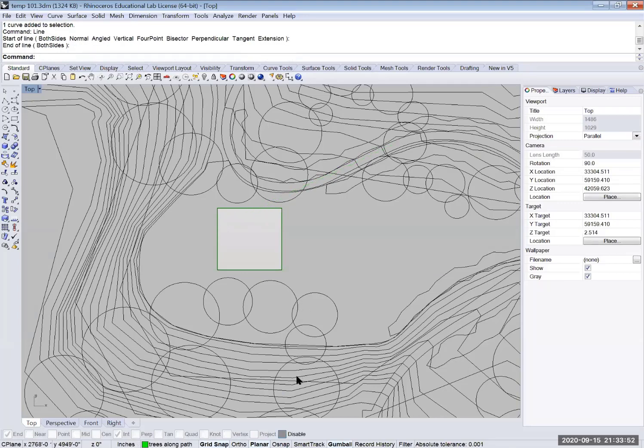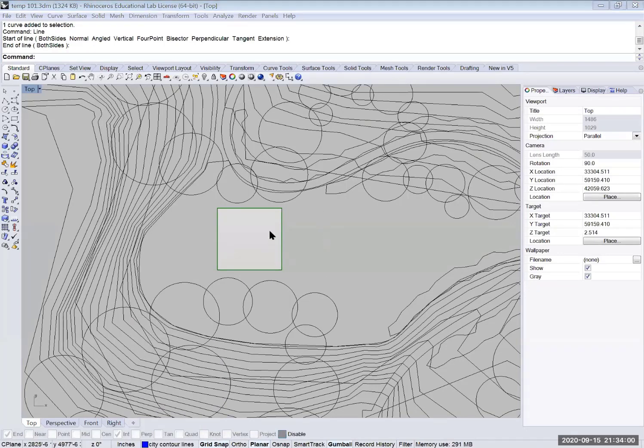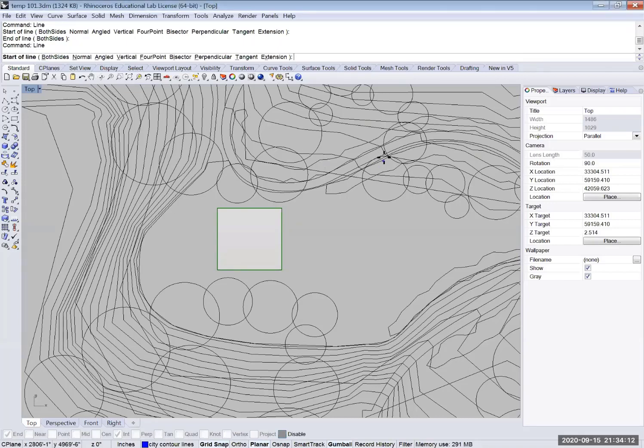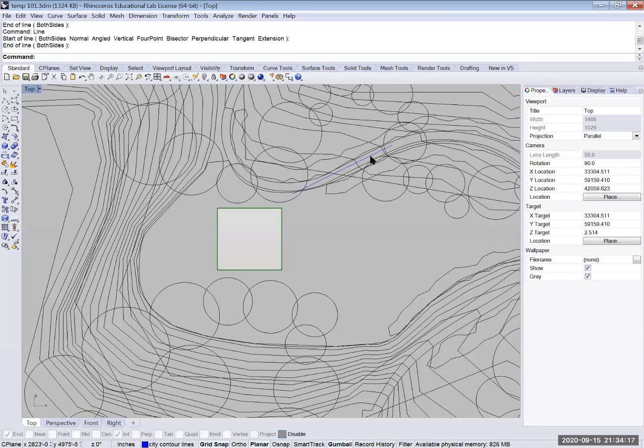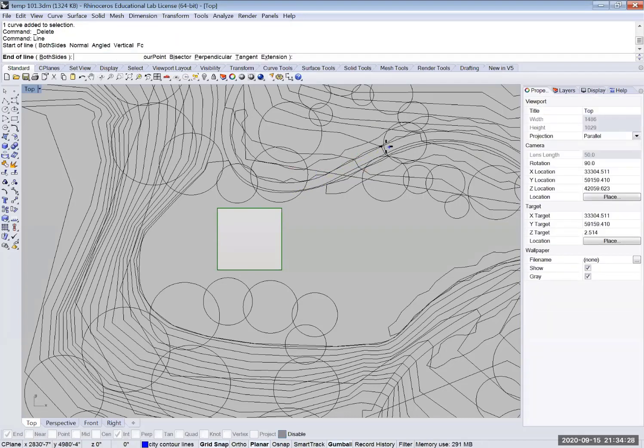And actually, I'm going to use a different color because I want it to sort of stand out. So let's try that blue color. I'm just putting stuff on whatever layer, so please don't do this. This is just as an illustrative means. So line, L-I-N-E, enter. You could think of this as my sight line, like what my eye is looking at if I'm looking at it straight ahead. I'm going to make it longer, somewhere in here, kind of off that way. You can see that my line of sight is actually looking at the side of the building, not the entry.